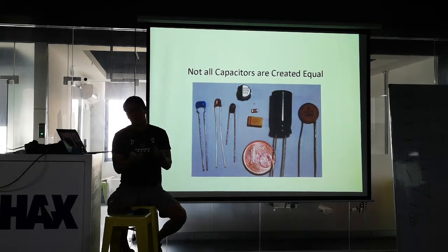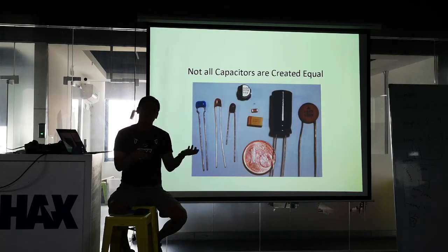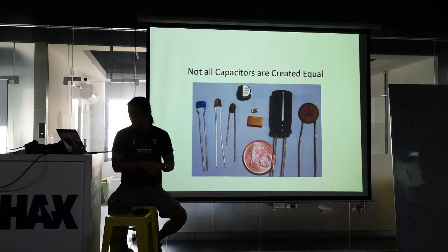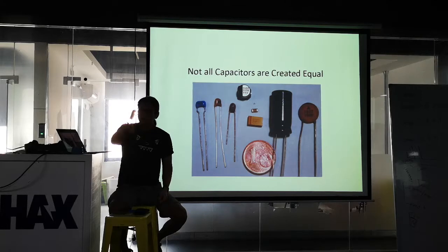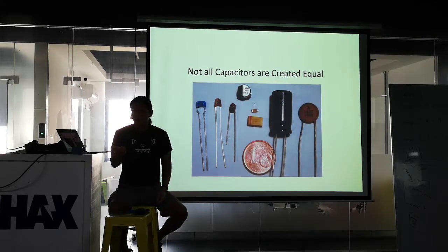So the unfortunate part about tantalum, or the fortunate part, I guess, is that they have a very high value for the size. So if you want a 100 microfarad capacitor, tantalum will be smaller than a ceramic capacitor. So a place where a lot of them are getting used is in the input power to, like, your laptop or whatever your IoT device is, right?